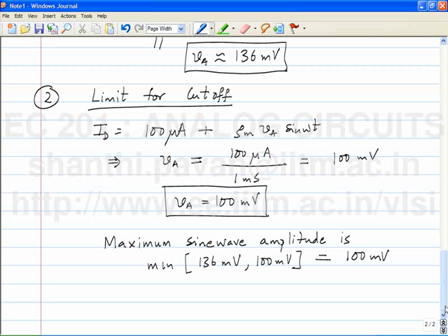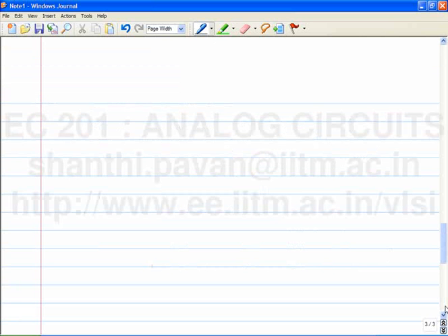And we seem to have forgotten one very basic fundamental thing, which is the total current being quiescent plus the incremental is alright, but the incremental value being related linearly to the input only happens when the signals are small signals. So you have to revisit. So clearly, once you assume things are linear around the operating point, these calculations are all very, very straightforward. So let's go and revisit again what is small signal.